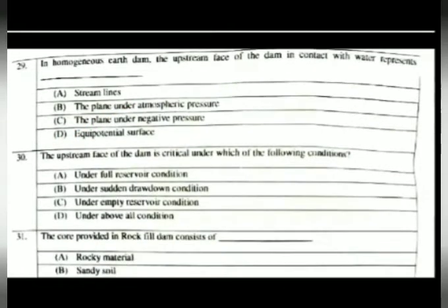Next question is, in homogeneous earth dam, the upstream face of dam in contact with water represents? And the right answer for this question is equipotential surfaces. The upstream face of dam is critical under which of the following conditions? And the right answer for this question is option B, under sudden drawdown condition. The core provided in rock-filled dam consists of? And the right answer for this question is option D, clay material.